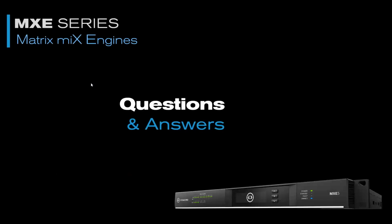I'll answer the next question. The question from Jeff in Sydney is: can the network audio span multiple subnets? The answer to that is yes. It can span; it's layer 3, as well as the control from the Omnio system, that's the OCA and Dante. You can span multiple subnets from that.